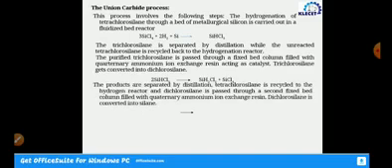Next, the dichlorosilane formed is passed through a second fixed bed column filled with quaternary ammonium ion exchange resin, and here dichlorosilane is converted to silane.